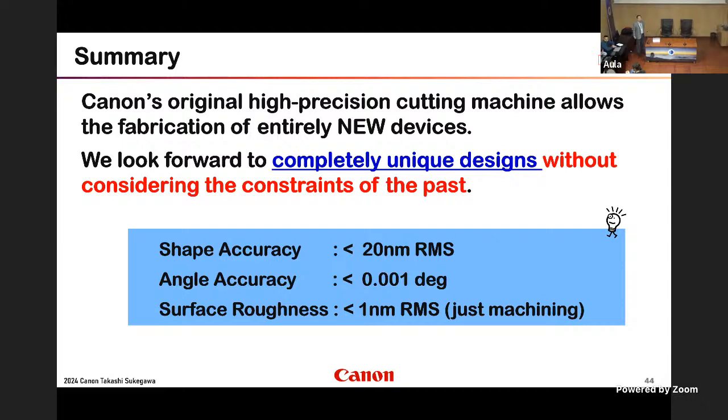50,000 lines per millimeter? That depends on our limitation. A groove width of 200 nanometers or so is possible. But the problem is, of course, machining time. So my answer is groove pitch is usually no limitation. But total machining time is a limitation for us. If you use a small one, or the UB for the 10 millimeter, we can provide 4,000 grooves per millimeter.